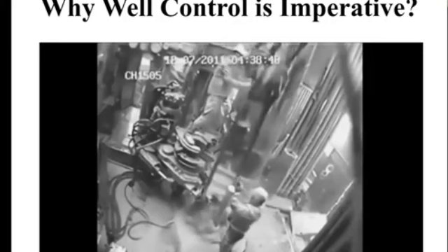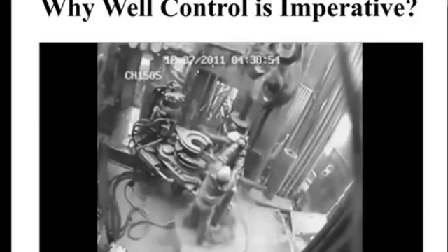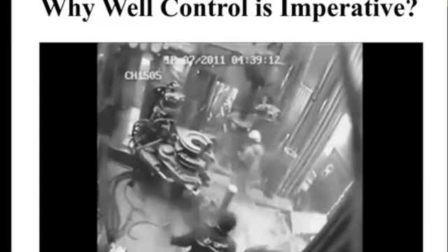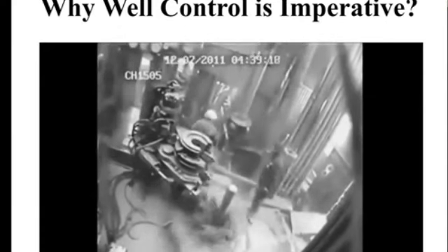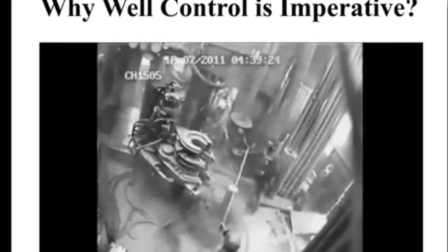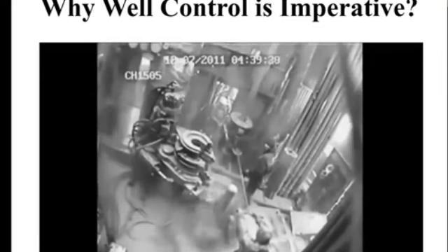And the other thing I would like to draw your attention to is, as the time passes, you see the situation gets worse, and I'll talk about the reason why. So it's almost 1 minute, right? If I'm not mistaken, or 30 seconds. And now you can see more and more formation fluid, I mean, the drilling mud at a higher rate is coming out of the wellbore, meaning that progressively formation fluid is entering the wellbore at an increasing rate.